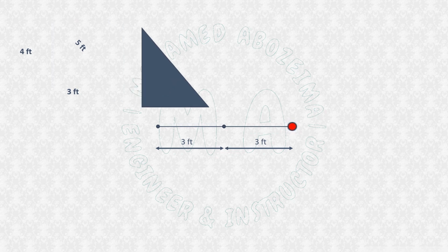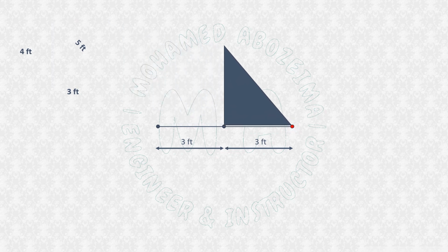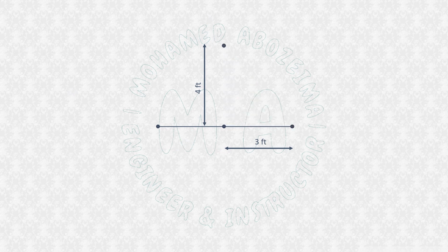Now move the meter till you have a 7 feet reading on it, which is the sum of 3 feet plus 4 feet. This makes a right angle. Drive a steel bar here. Again, look from this direction and drive another bar 4 feet away from the center point. After finishing, we will have our axis, from which we can spot any point relative to it.